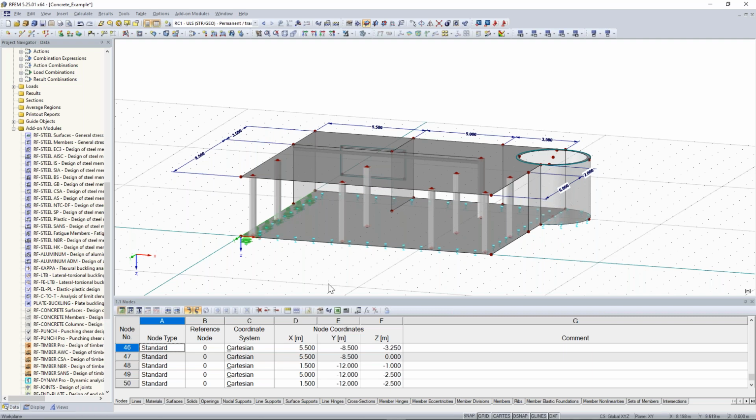But what is a service life prediction? Allow me to add something to that, because the same person asked about the rebar area and how flexure and shear is calculated. It's also possible to design all these things with RF concrete. And once you calculate your structure with RF concrete, you'll be able to see all the details concerning the rebar area for flexure and shear. But yeah, this is possible.